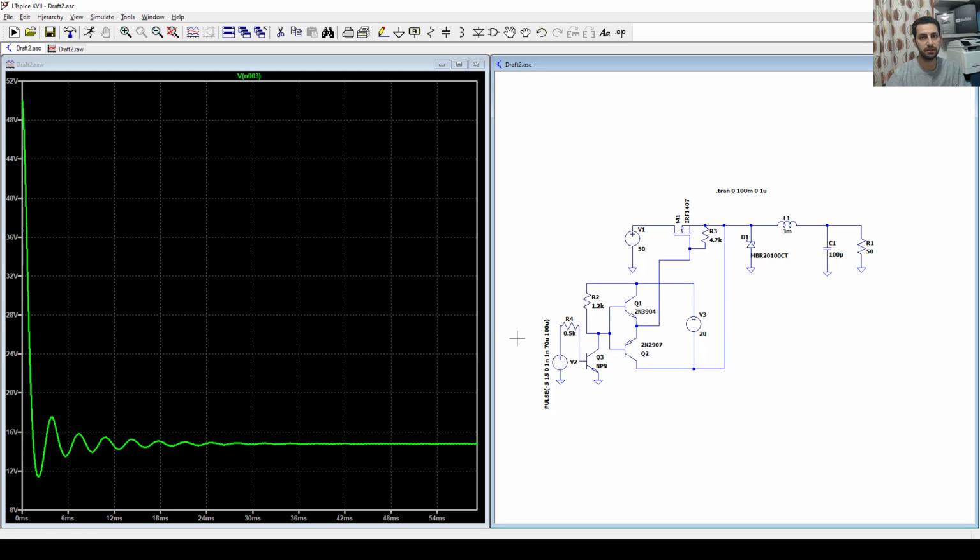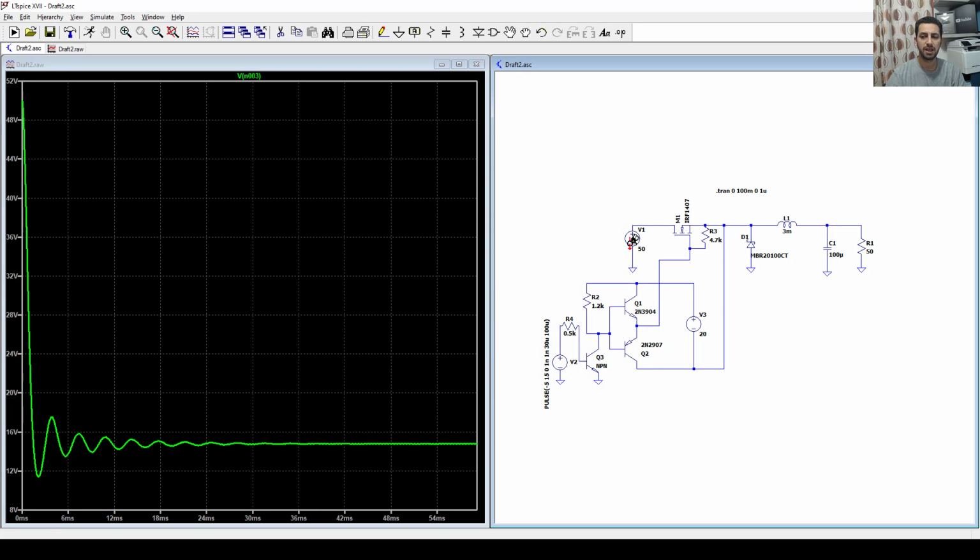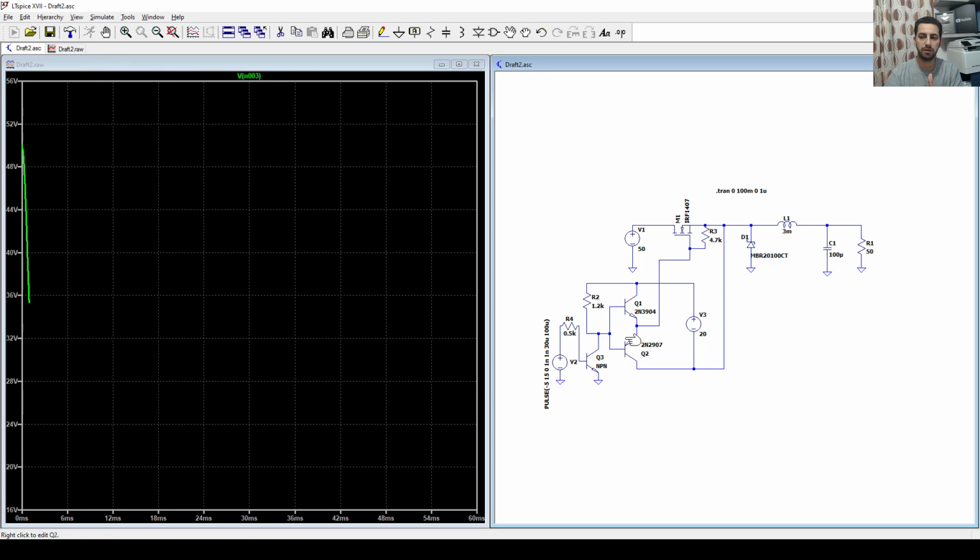Inverted PWM means the duty cycle is not the main controller here. It is 1 minus the duty cycle that is the main controller, because the on time is reciprocated to off time, and off time is reciprocated to on time. So if I want to get 70%, I have to drive it by 30%. Okay, so the driver here is 1 minus delta, not delta. And that happens if you have an inverted driver. We have an inverted driver here.